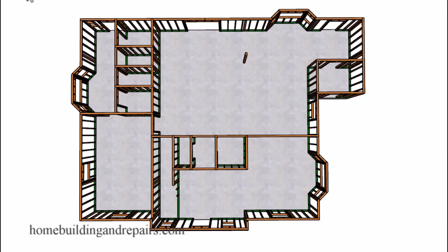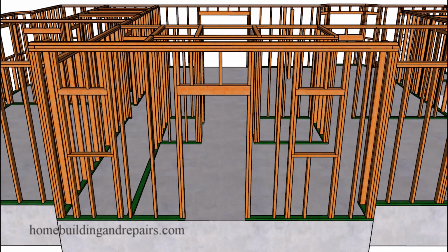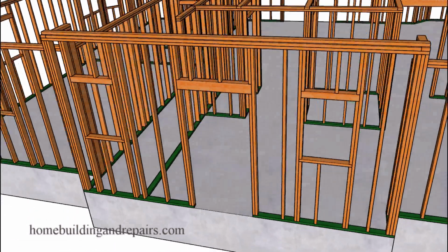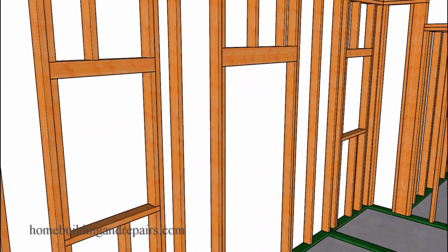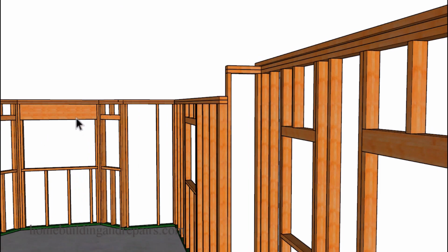Here is a little something that you might not be aware of, especially if you've never designed a house before or remodeled one. And that will be the fact that the window headers and the door headers, the bottom of each, will usually be installed at the same height. So in other words, the top of the door will dictate the height of the top of the window and not the other way around,